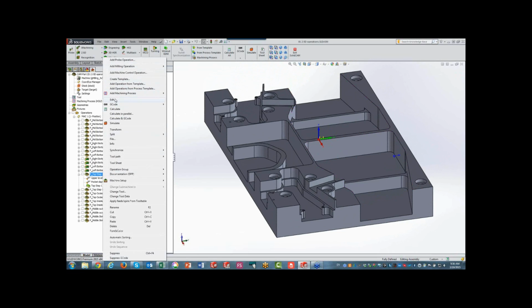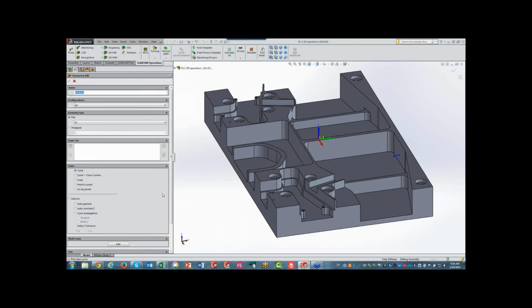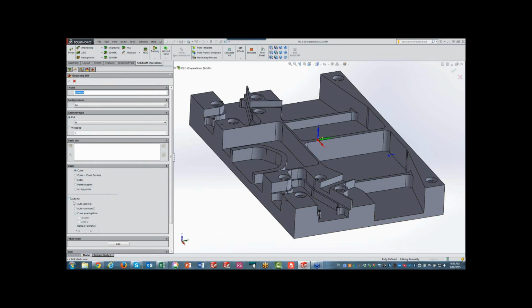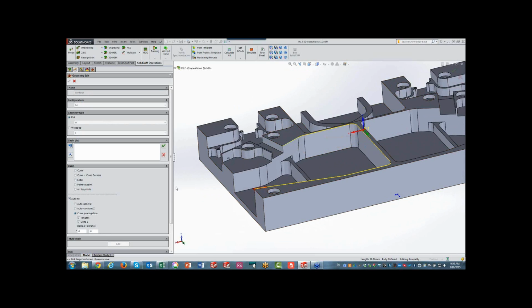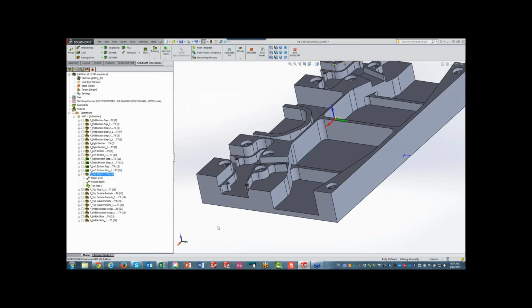I'll just go in there and I'll just edit the part just for a moment. I'll do that just for this part. And I'll just create a geometry and I'll show you exactly what's involved. I have to do the following. I have to say, okay, I wanted to have a chain go automatically up until a specific point, and I'll start from here, going up until this area over here. I can't continue on down because it'll continue all over there. Now I'm going to do what we call curve plus closed corners, and I'll click on this area over here. And then I'll just click on this curve, and I'll just accept this the way it is right now, and then it'll mark my open edge as shown over here. So you see, creating a geometry over here is not always straightforward. Okay, I'm not going to accept it because I already have my geometry here. I just wanted to show you what's involved sometimes when creating chain geometries.